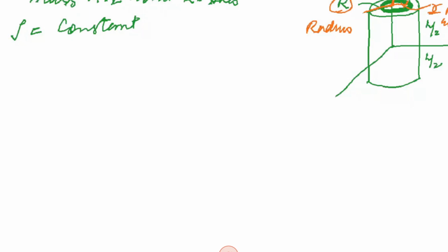So how can we calculate the mass moment of inertia here? We need to consider dv of this elemental shell. Now dv will be, firstly, the circumference, that will be 2 pi r, I'm talking about small r, multiplied by the height. Total height is h, right? Multiplied by the thickness dr. So dv is 2 pi r h dr.